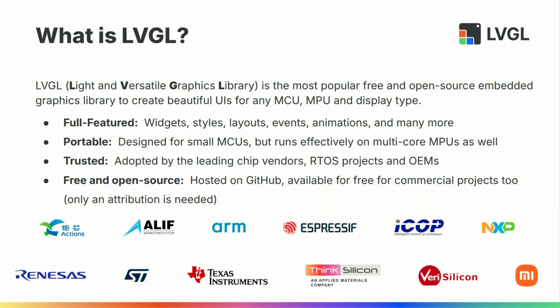It's a portable and scalable solution. Originally it was designed for small microcontrollers having only around 100 MHz of clock speed and only a few hundred kilobytes of RAM and flash, but due to recent updates it runs effectively on NPUs as well. We have a lot of Linux display drivers like Wayland, DRM or the frame buffer device, and we are also working on OpenGL support.